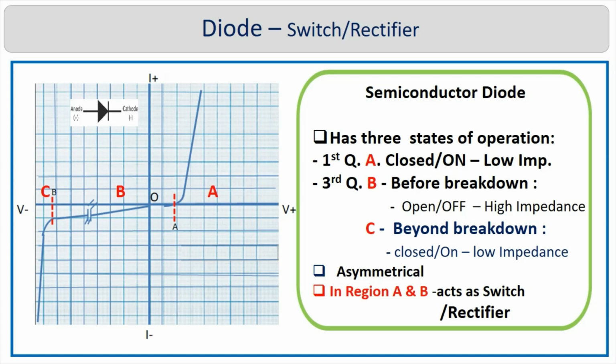The diode VI graph exhibits low impedance in forward bias and high impedance in reverse bias. Further increase of reverse bias leads to device reverse breakdown and enters into a low impedance region. A diode is used in forward low impedance and in reverse high impedance, that is, without entering into the reverse breakdown region. This asymmetrical property makes it suitable for rectification, switching, signal detection, etc.